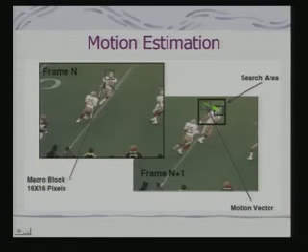In fact, an MPEG compression stream consists of what we call I, P and B frames. I frames are nothing but JPEG compressed frames. P frames are what are called predictively compressed frames. That means, for P frames, we actually exploit this kind of temporal redundancy.